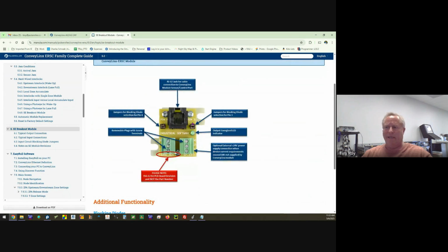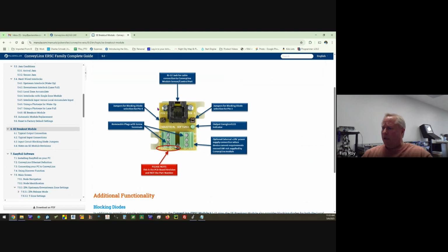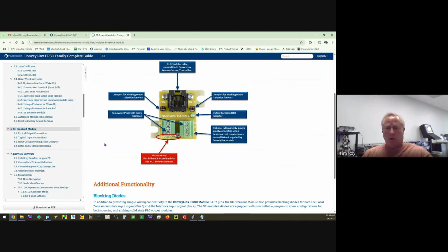This is just a little bit more in-depth information about that breakout board. One thing, if you are going to use this with a PLC, the output from us will be okay because it's basically kind of isolated relay style. But our inputs, because we auto detect when it comes to your sourcing or sinking output card, and you connect it to one of our inputs, there's going to be leakage current, and the input will always be on.